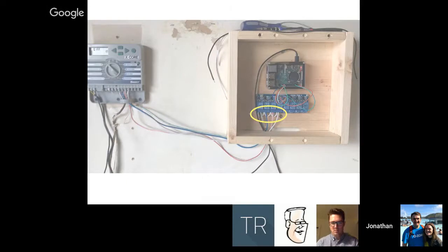These are where I have the sprinkler zone wires coming out, and then also where I'm daisy chaining the power. This cool little blue line is half of my 24-volt AC. If you could tell where this blue line is ending at the controller, it's kind of split into a Y. That's my single 24-volt AC power line coming in, split between two. So one of those is the power. The other one is connected to this common line.